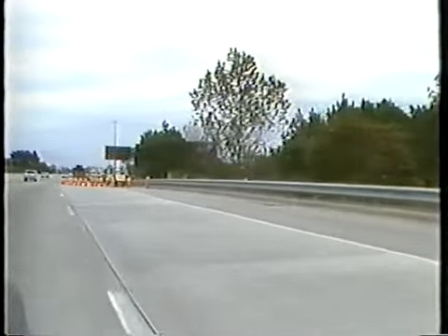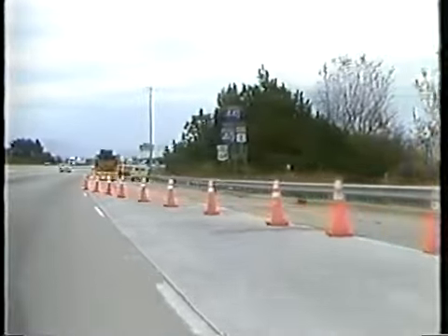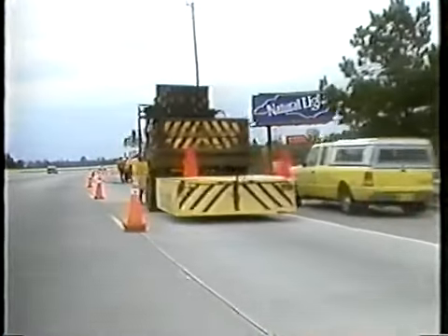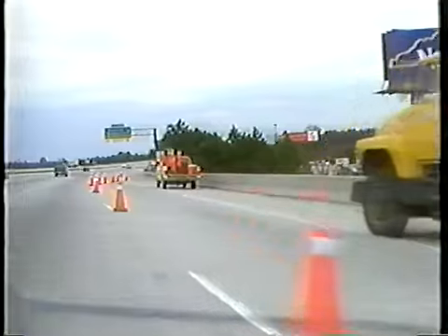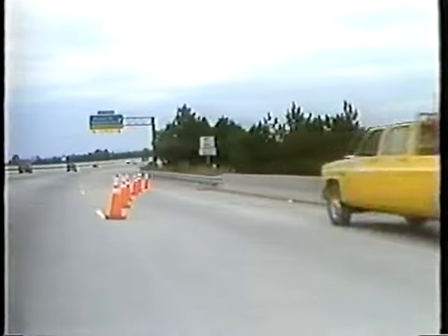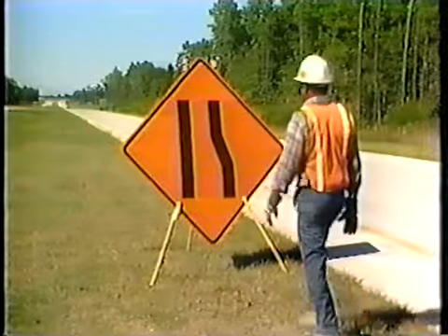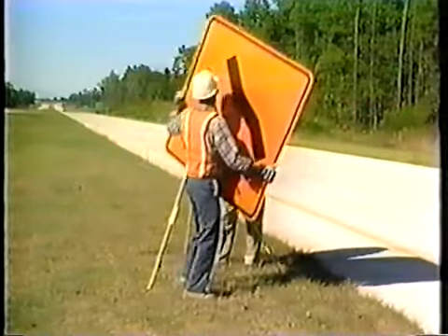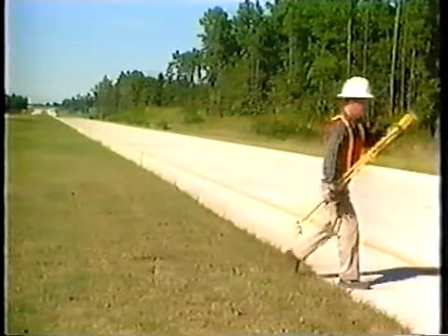Again, evaluate traffic controls by driving through the work zone after all the devices are in place. Remember to put yourself in the place of the unfamiliar driver, the one who is not anticipating your presence on the roadway. Now the work activity may begin. After the project is completed and all workers, materials, and equipment are off the roadway, the traffic control devices are removed in reverse order of installation.